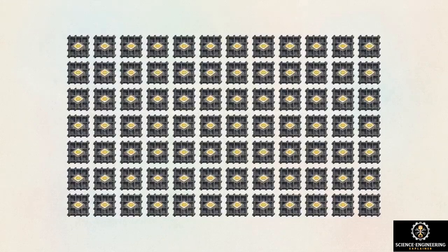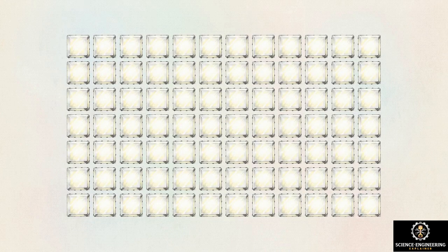This diagram illustrates Mini-LED's approach. Instead of a single massive backlight, the source breaks apart into thousands of tiny, individually controlled zones. Through local dimming, it completely cuts power to specific zones behind dark areas, halting light bleed at the source.